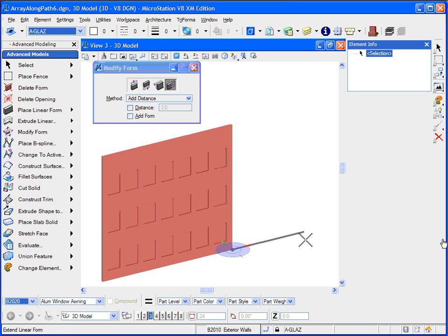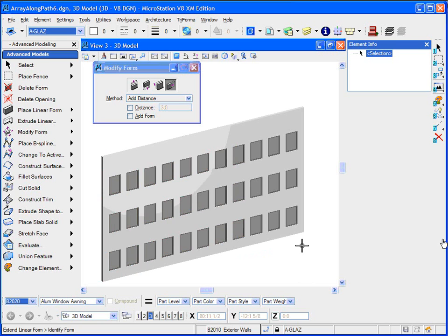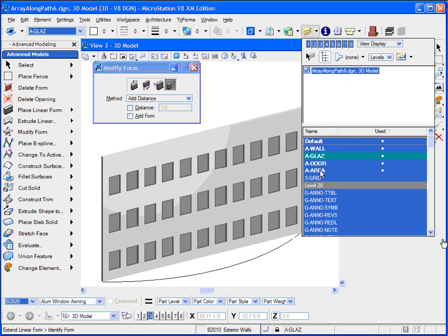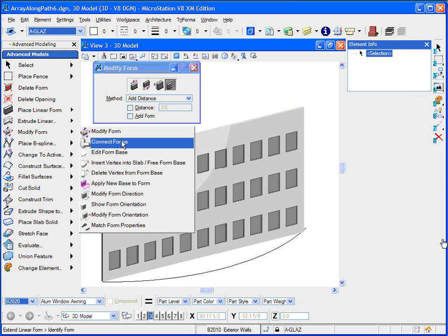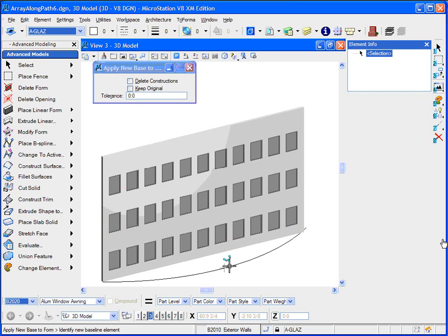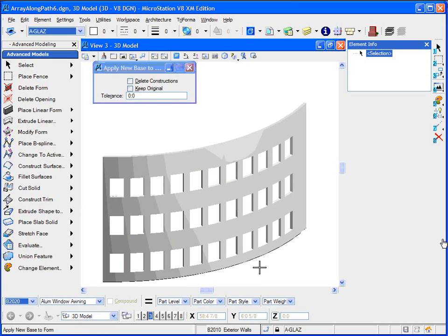can basically build any kind of template using the template tool. So I've already had this element template built, and now I'm just applying it to the facade. You can build different types of element templates that do different things for different projects. And then in this case, I want to take that flat facade and have it modify itself to an arc to make an arced wall.